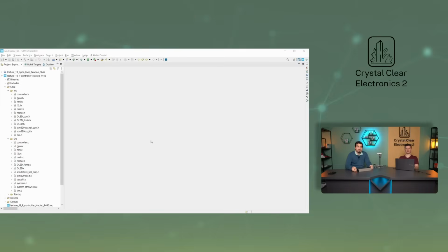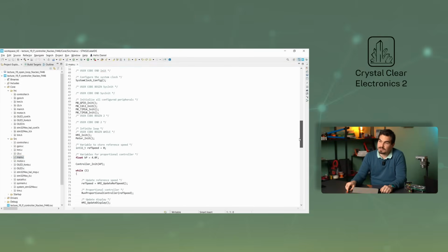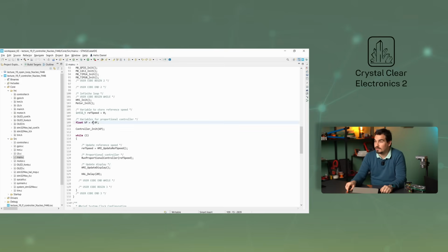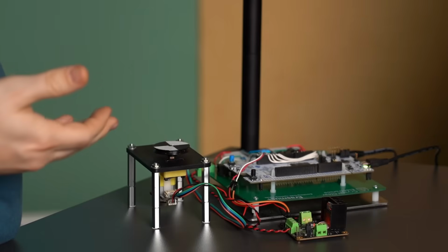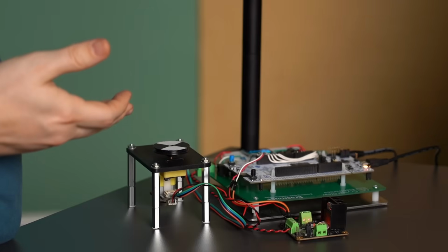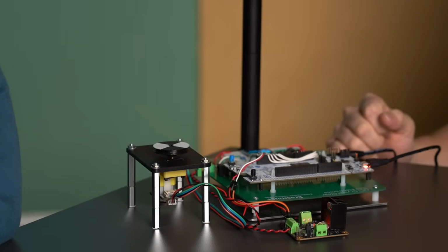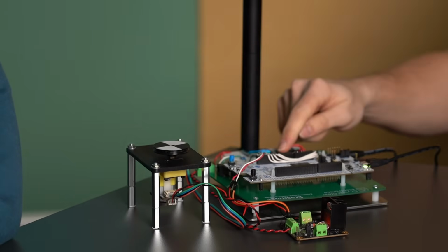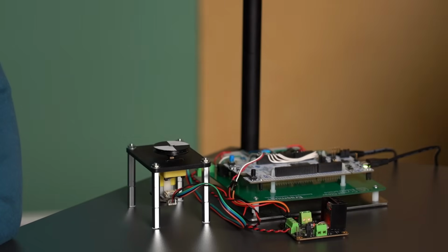The main.c file contains the setting for the Kp value. Change its value from 4 to 20, upload the code, and set an arbitrary set point using the left and right buttons. We can see that the motor is spinning back and forth, unable to adjust to the given value because it is too forceful, always falling over the other side. If we reduce the Kp value from 4 to 2, we will have too much residual error.